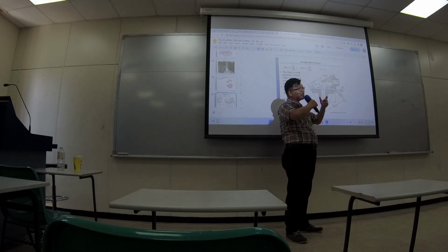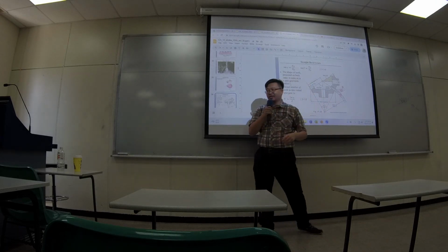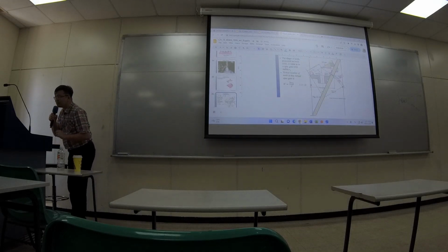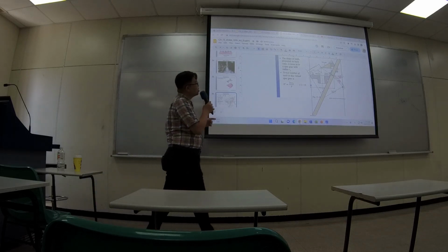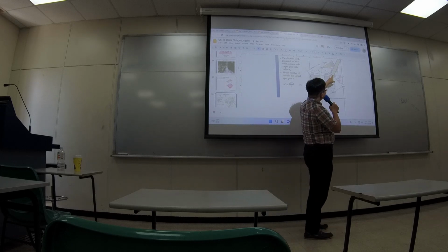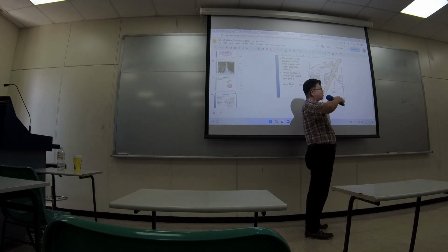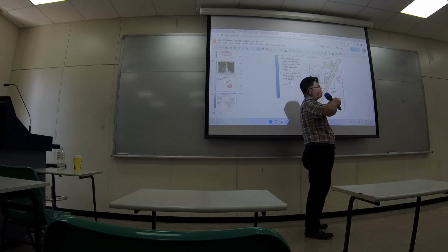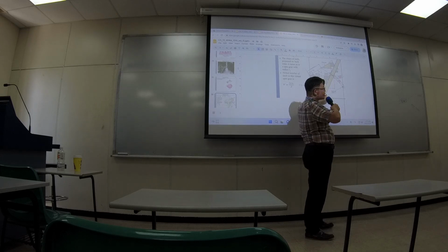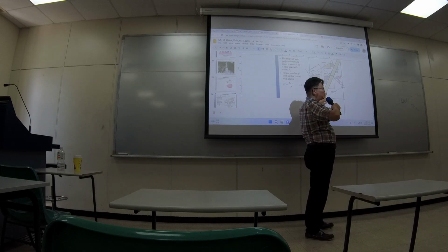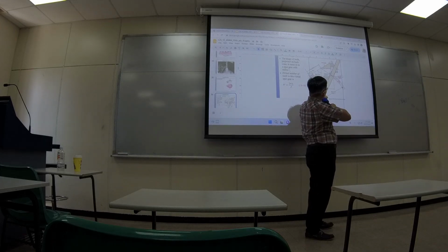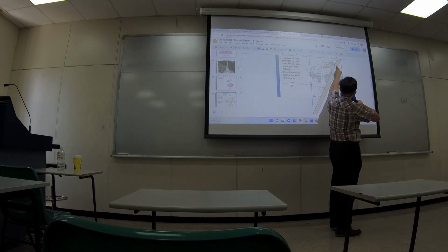But how do you compute the size of everything? They generate so-called virtual gears. The local conjugate behavior behaves exactly like two virtual spur gears, where this one has a center right here, and the other one has a center somewhere here.